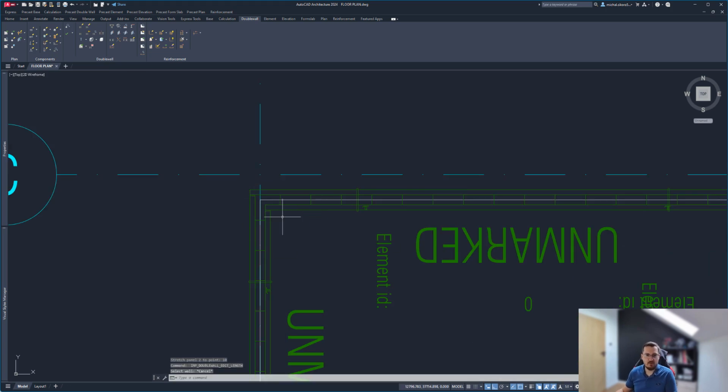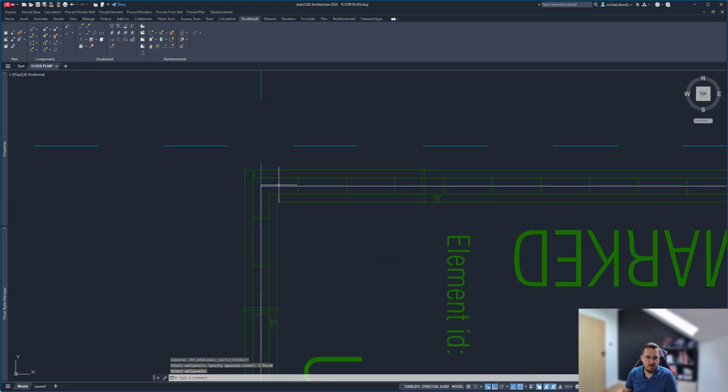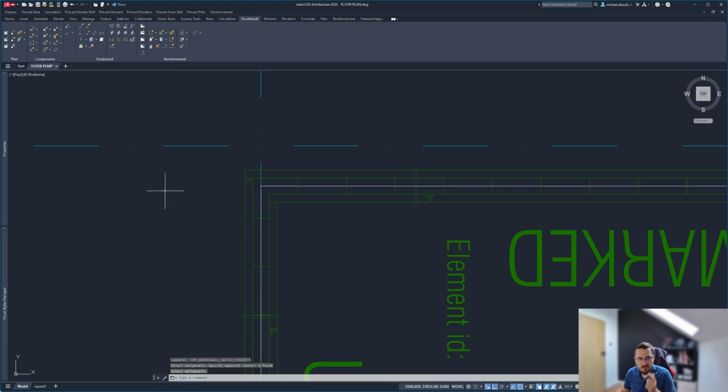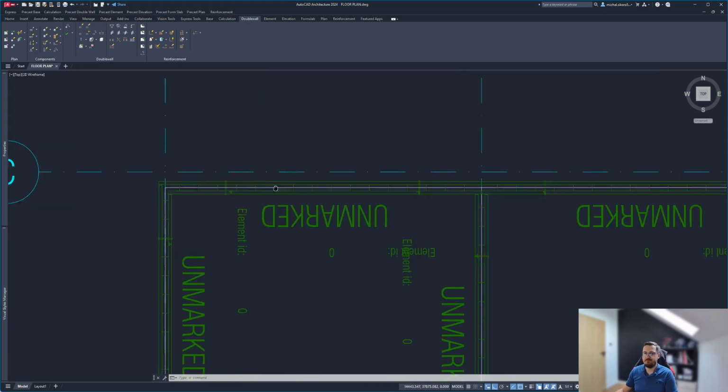And now we have a nice little connection. And of course, if for some reason I need to change the priority of that joint as well, there's an option here. I can just select that and it will switch that priority for me for this wall. So even though it's not like an automatically created joint, the software still knows that, yeah, switch panels, basically.